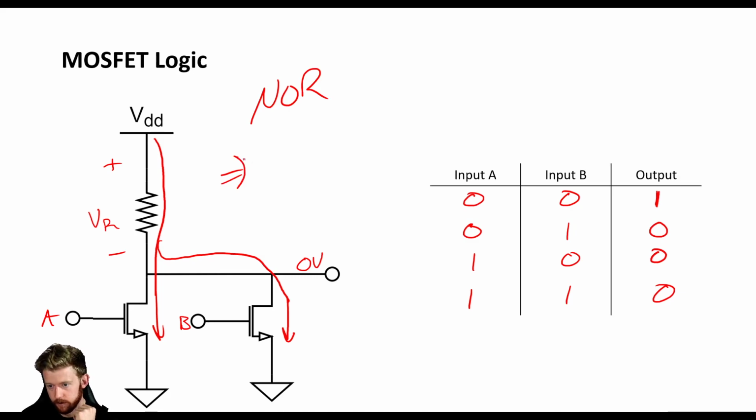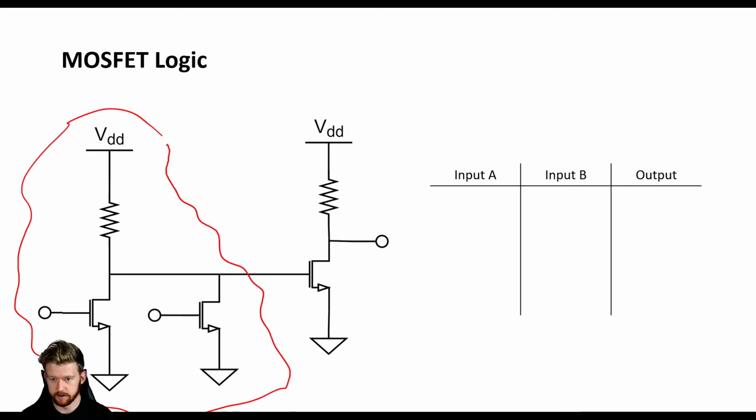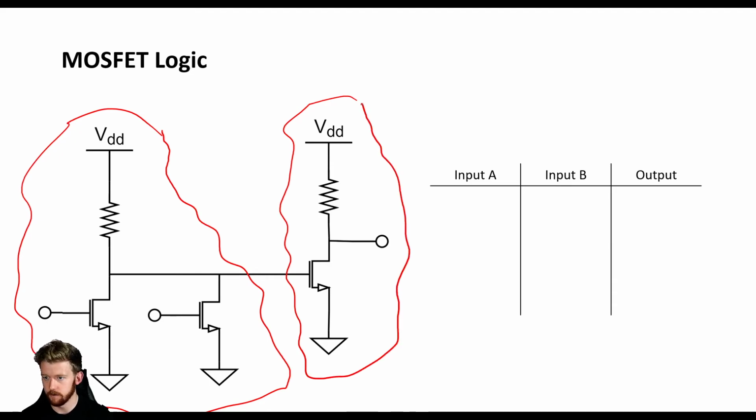which if you remember has a curve and a point at the end and a dot. And it's the same thing as an OR gate, which I'm trying to make that point very clear, followed by an inverter. Okay? Now, if we take a look at one more example, we can see that we have two sections here that we're going to try and separate. And usually, sectioning off your circuits can give you a pretty good idea of what's happening. So if we can section these off clean as inputs and outputs, then we can maybe make a little bit more sense out of it, okay?